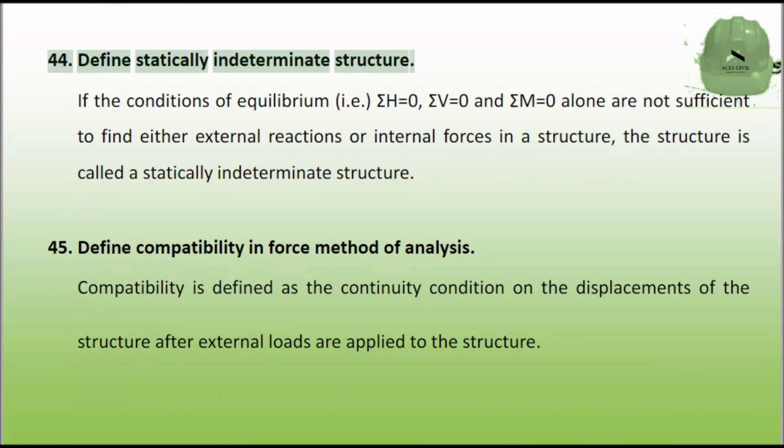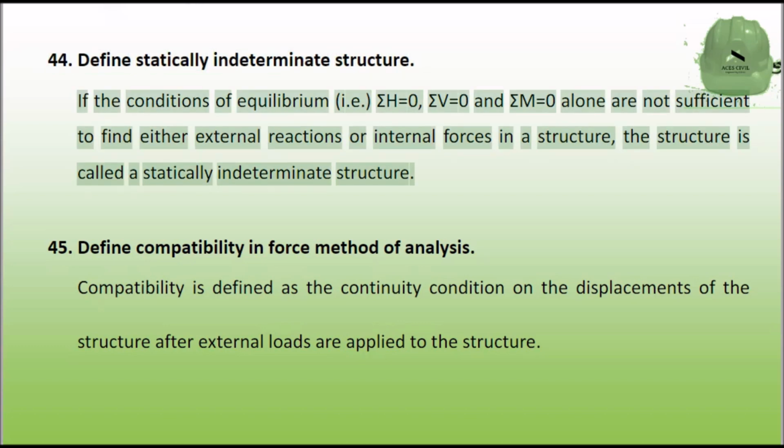Define statically indeterminate structure. If the conditions of equilibrium, i.e., ΣH equals 0, ΣV equals 0 and ΣM equals 0 alone are not sufficient to find either external reactions or internal forces in a structure, the structure is called a statically indeterminate structure.